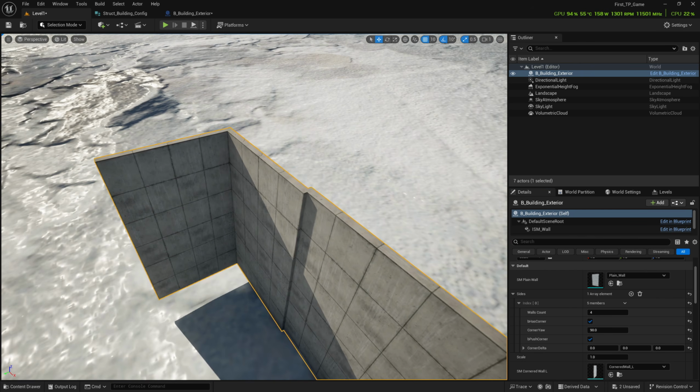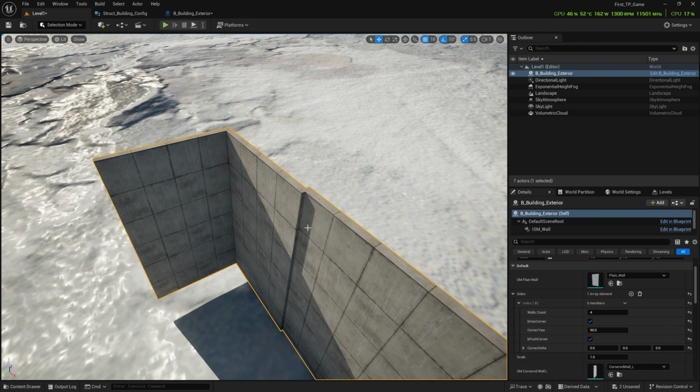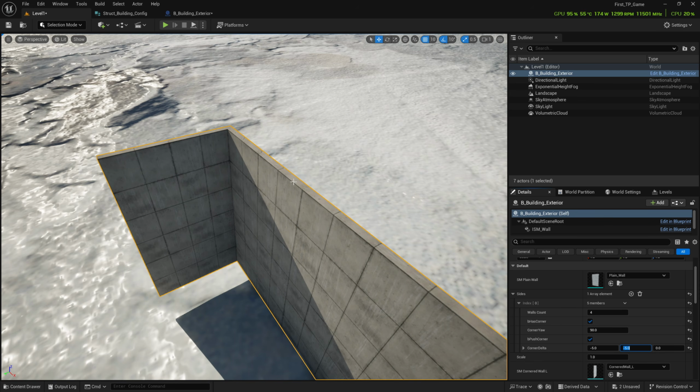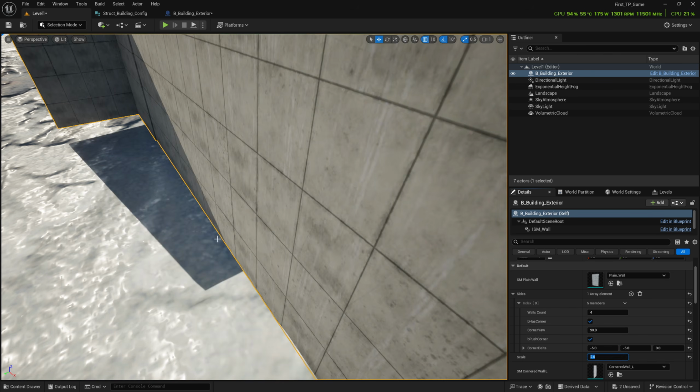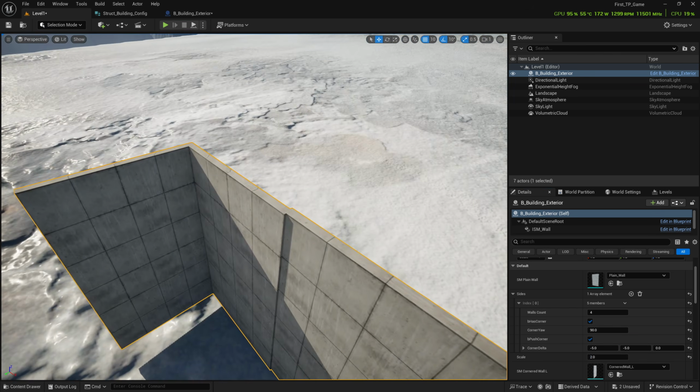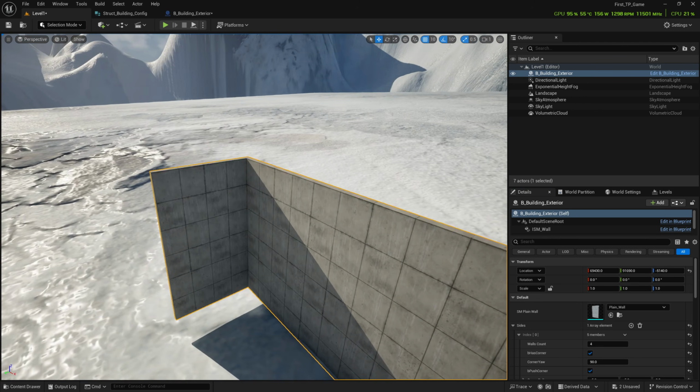Now this is a scale 1. If you have a higher scale, then the value can vary. So first decide whether you want to follow this or not. Because if you are following the 1 scale, then it will go -5 in the X because it was overlapping, and then -5 in Y to get it perfectly aligned. But if you scale this up to 2, then the values have to be increased. Okay, 2 ways.